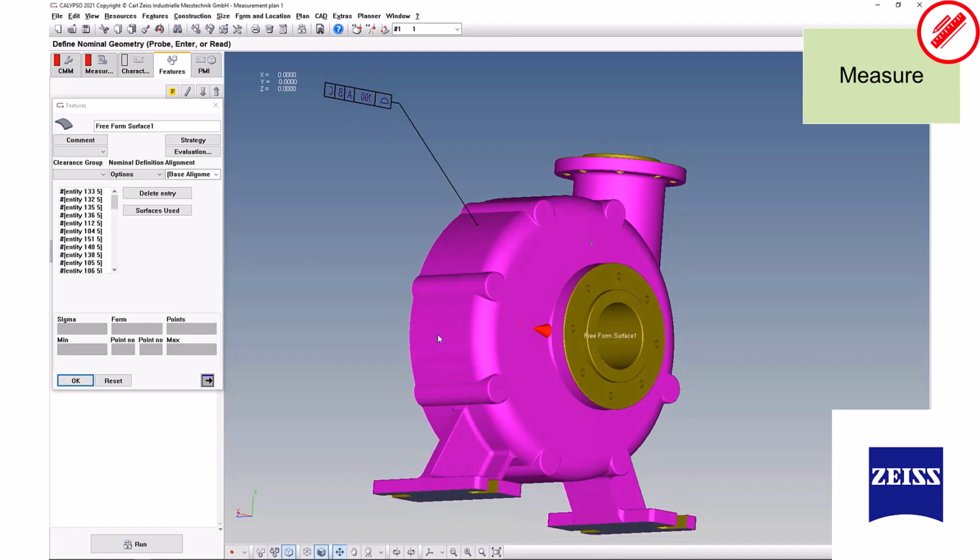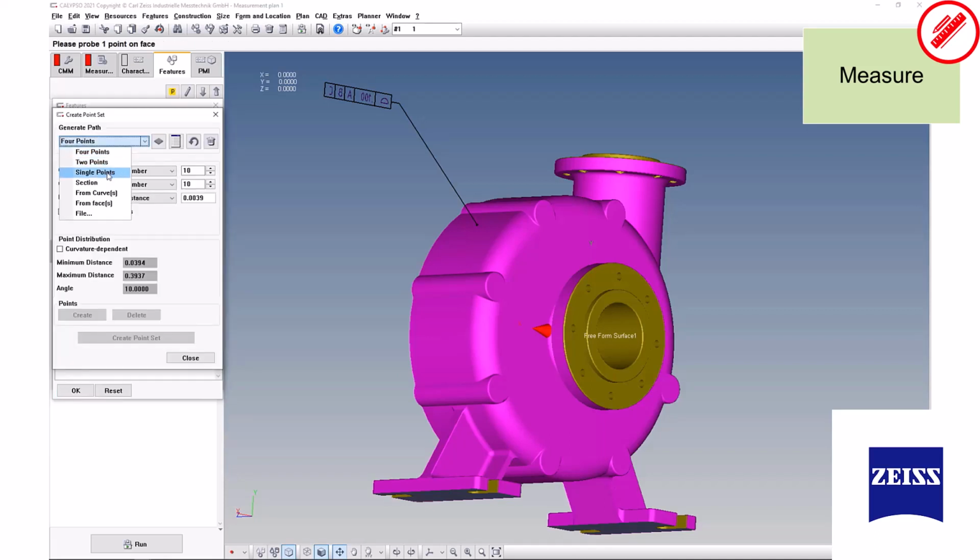Now this is a very difficult measurement on a CMM just because, as I mentioned, you can't get a tactile probe to really touch off on all that area. You could, but it would take an extremely long time to scan. So a CT data set analysis like this is going to be much more ideal from a time standpoint, and you can actually check all those little nooks and crannies. So what I'm going to do is just program the strategy here to cover all those little areas.